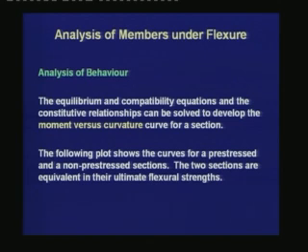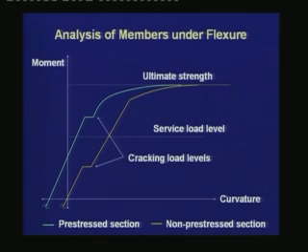The two sections are equivalent in their ultimate flexural strengths. The idea of studying the behavior is to understand the effect of prestressing in the moment versus curvature curve in a section.